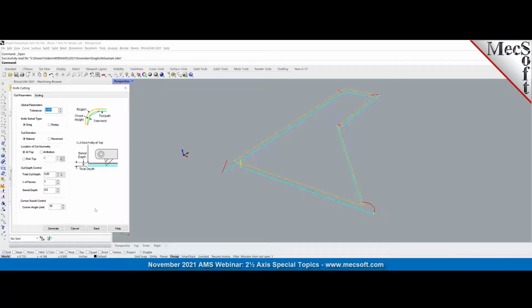It's got to be slightly inside the material. And that's what we've done here, and you can see the toolpath. I can simulate that. We have selected this knife as a swivel type knife, and then, very similar to a profiling or engraving operation, we selected the curves. But you can look at the corners. You can see the knife goes up to here, picks up, does a rotary transfer motion, and then comes back down in here, does the orientation of the axis of the spindle, and then goes cutting in that direction.